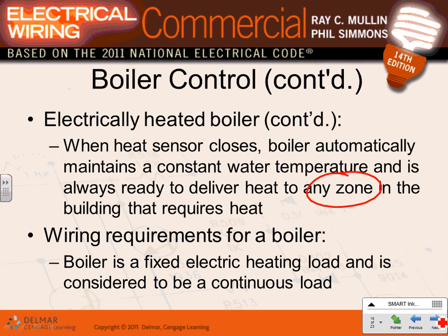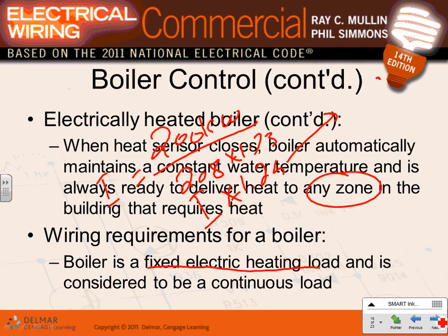How do you wire it? Wiring it exactly like a continuous load. How do you wire a heater? 1.25 for the branch circuits, 1.25 for the overcurrent device. Done. So if you take the 200 kW, divide this by 208, don't forget 1.73, give you I, take your I, multiply it by 1.25, this will get you a conductor and also an overcurrent protection device. Done. See how easy that is? We've done it a couple of times. So that's my heat requirement.